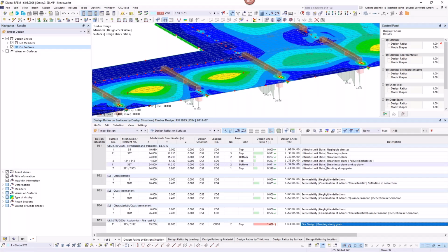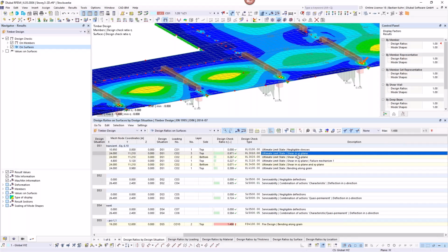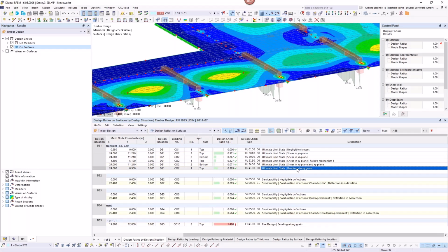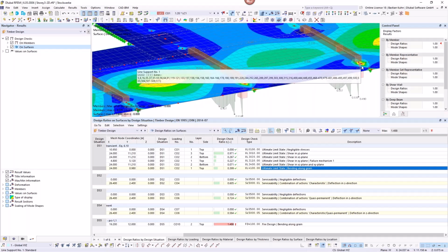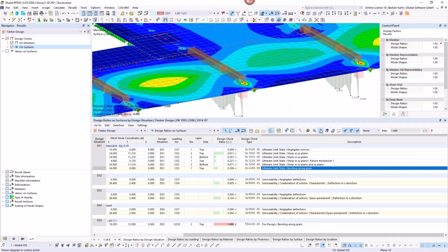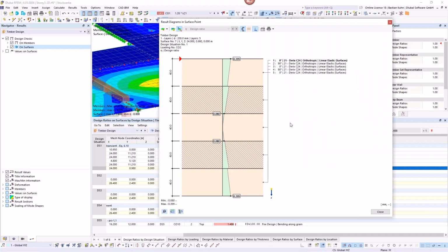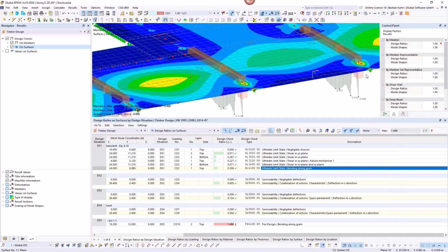Before we do that, we also take a look at the other loadings inside here. The shear for the punching through area is design giving in here on this part. That's the usual punching through area that you want to take a look at. We can maybe also take a look at the stress over the whole section, because I think that's always nice to see. And you see for the bending how the stress is transferred into each layer of our section or our surface.